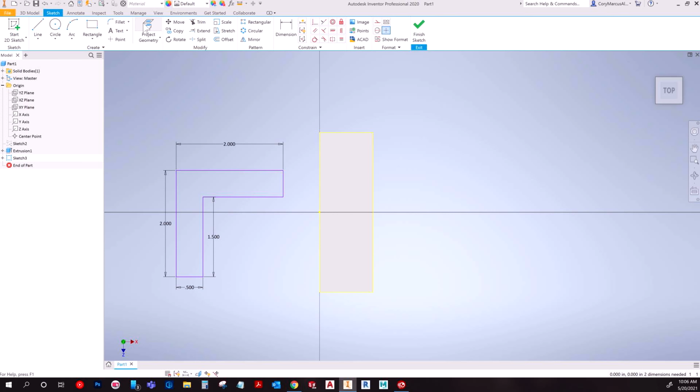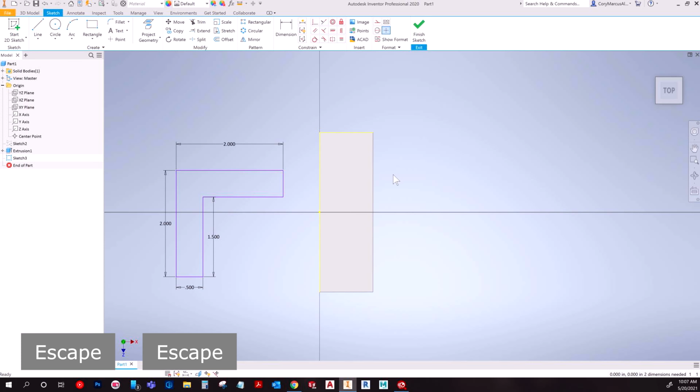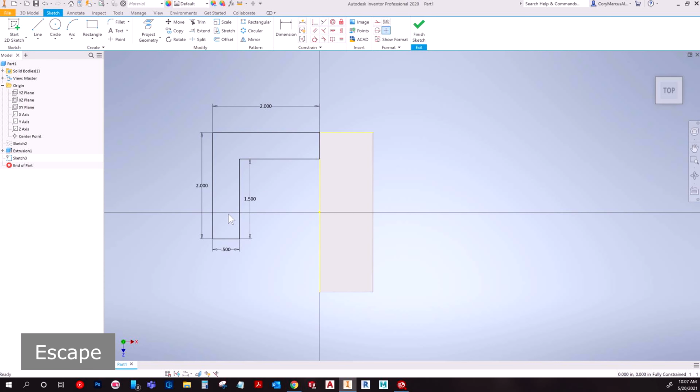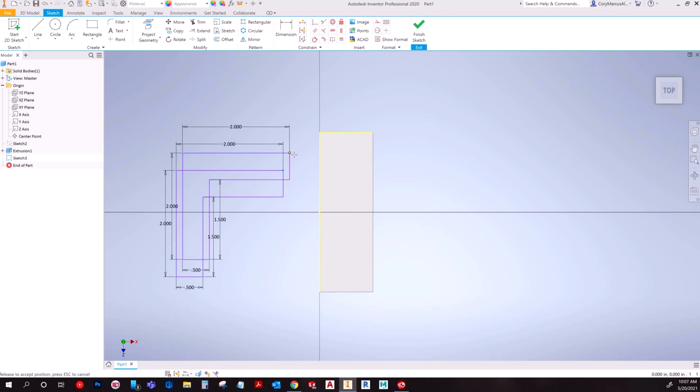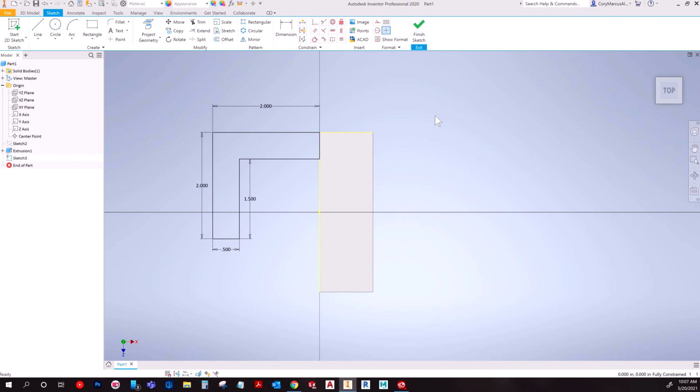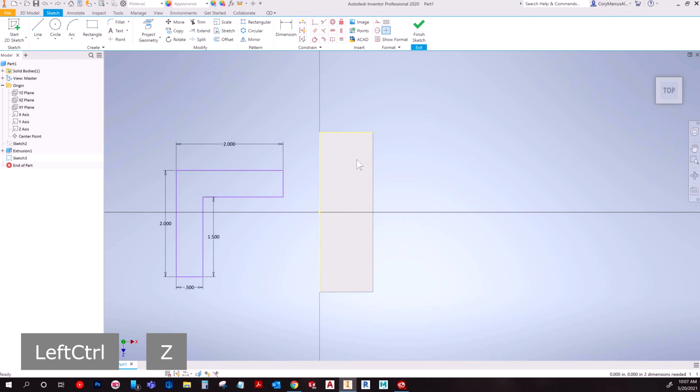But what you need to do is hit project geometry and click this face. If you notice, it's highlighted. I guess technically you could also hit the edges if you don't want to use it all. But you're going to tie this part into this area, and you could just lazily use a coincident, and that would do the whole thing. But it's really hard to edit. I try to avoid using coincident where I can, but since you're just starting out, you are welcome just to grab it and let it go right there. That's pretty straightforward.